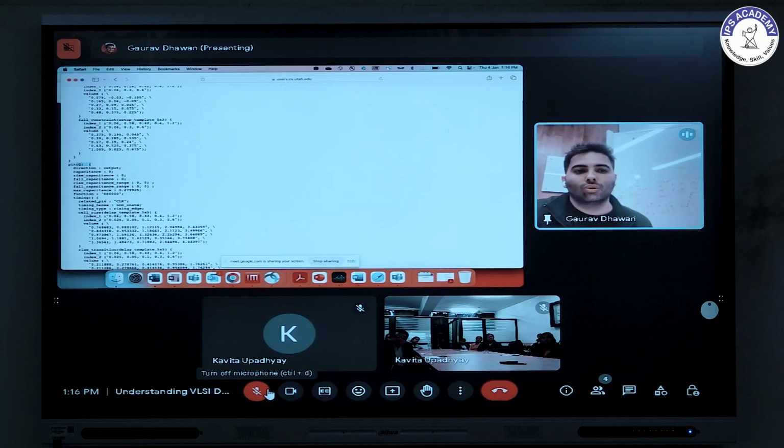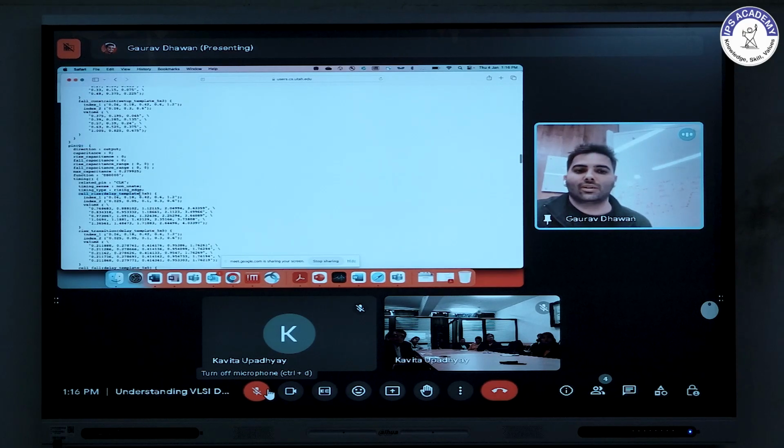This arc is from clock to Q, and the timing sense and timing type you can leave. Cell rise means we are trying to see how your delay will look when your output is rising. Cell rise means it's a delay. Index 1 represents your slew, different slews. Remember we have seen the unit at the top, this is in nanosecond. So this is 0.06 nanosecond, 0.18 nanosecond, 0.42 nanosecond, for different slews.